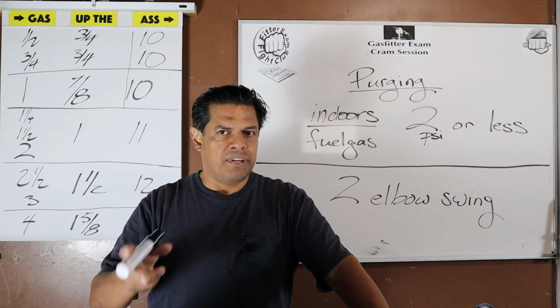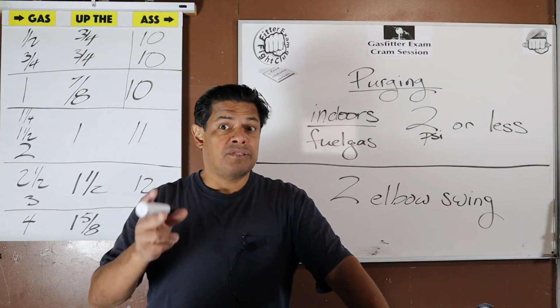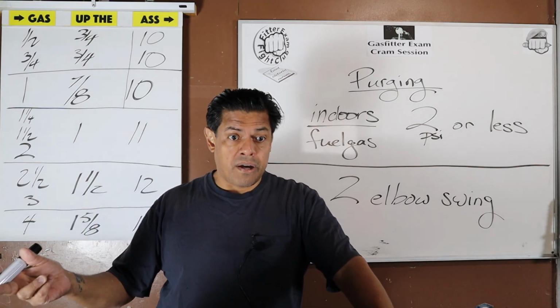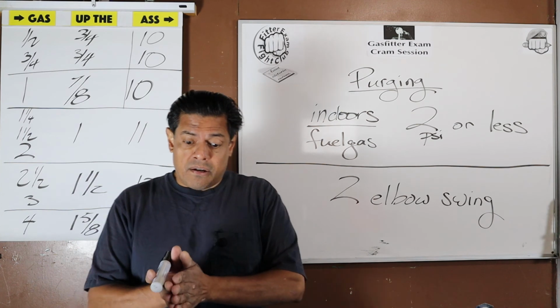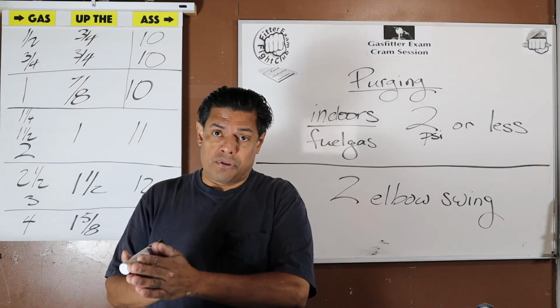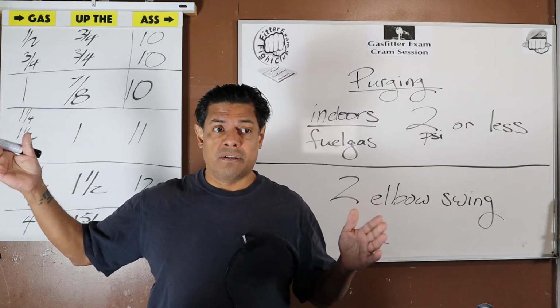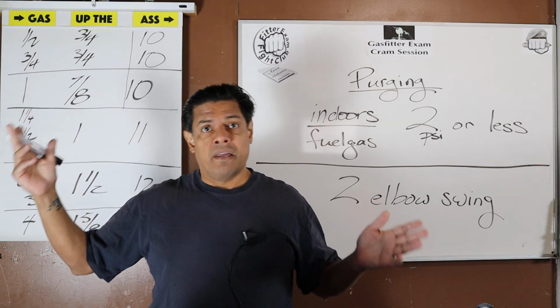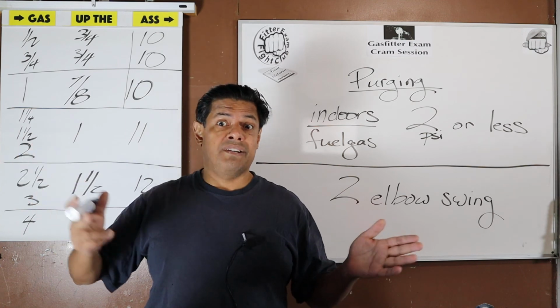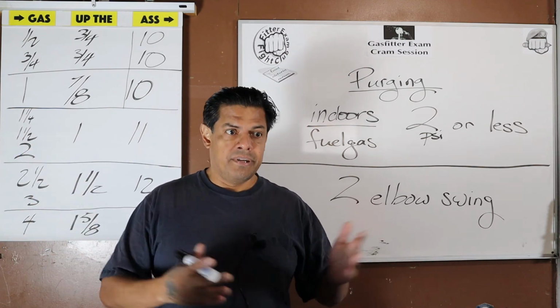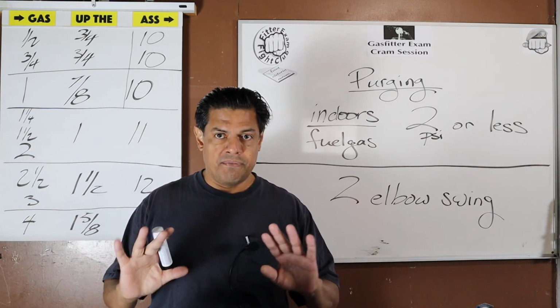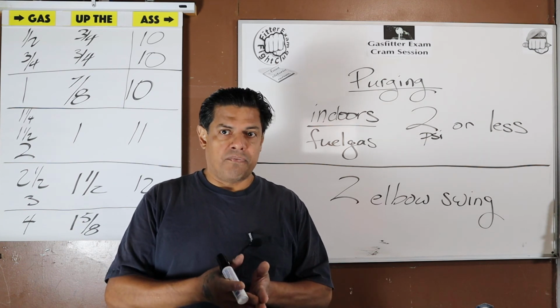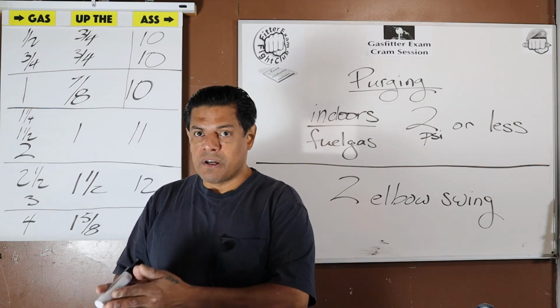The less potential leaks, the less chance of having a leak. So I always say, the shortest distance between 2 points is a straight line. Well, try and find the straightest line possible, given the piping and the fittings you have. I always go for the least amount of joints possible.